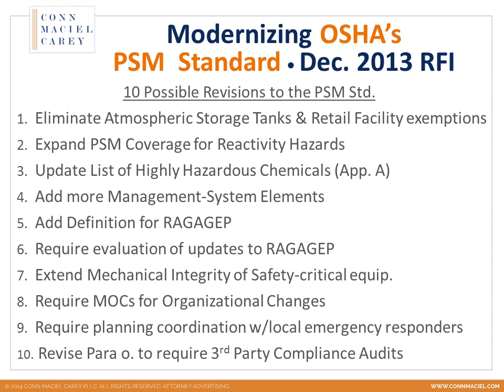But the OSHA Review Commission issued a decision in 1997 that considerably expanded that atmospheric storage tank exemption to cover flammables stored in storage tanks, even if they are connected to a process that is covered by PSM. That is not what OSHA originally intended by that exemption, according to the agency. And so the agency is asking for comment on closing that gap that was created by the Muir decision in 1997.